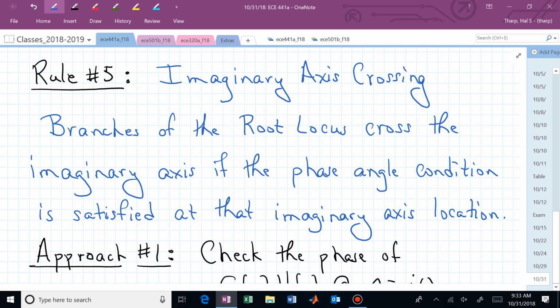If I now scrolled back up, so I'm relying on your memory now, which I assume is much better than mine, but if you go back and calculate the phase of those poles and zeros at j square root of 2, you can draw those 3 angles, 2 from the poles and 1 from the zero, add those up algebraically, and it better produce minus 180 degrees.